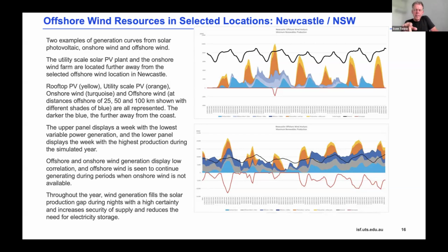And the other extreme, the lower panel, shows that we produce almost the entire week far more electricity than we actually need. And then we have that red line below the zero line, which means negative demand, which is basically storage. So this is what we need in terms of storage. The engineering job is, what is the optimal size for the storage in terms of capacity, so we can always meet the demand every second? And in terms of capacity in megawatt hours, that the storage technology, the battery or pumped hydro, will not be empty while we still do not have enough generation. So that is the exercise.